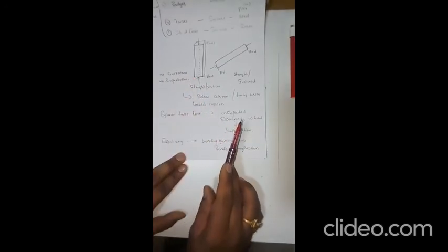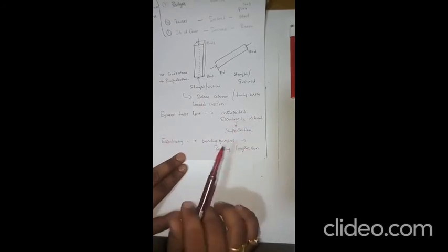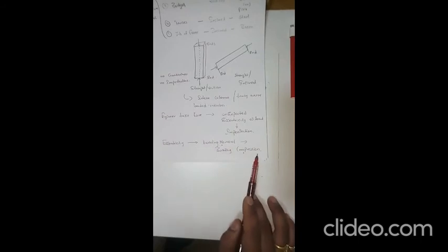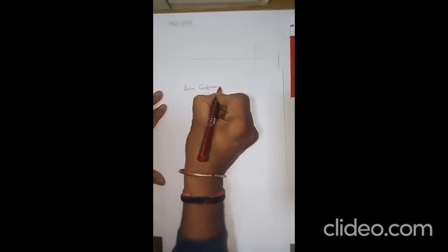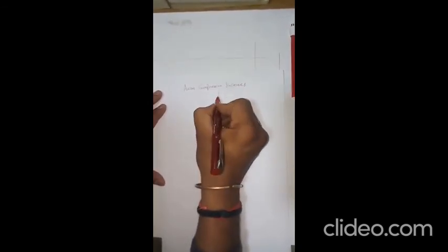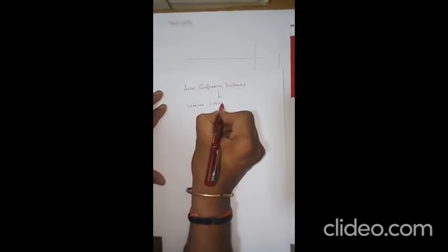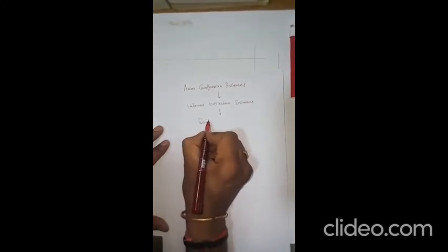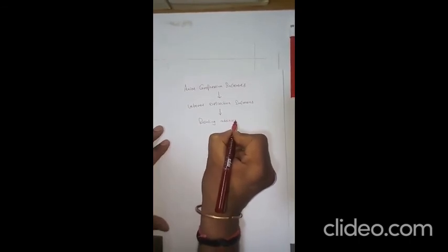When your axial load in the column is more, obviously the lateral deflection also increases, resulting in additional bending stress. Make a note. Understood? Apart from the axial load, the unexpected eccentric loads create a bending moment, and it creates bending compression in the column. So when axial compression increases, what happens? Lateral deflection also increases. Why? Because of the unexpected eccentric load, which increases the lateral deflection, resulting in additional bending stress.